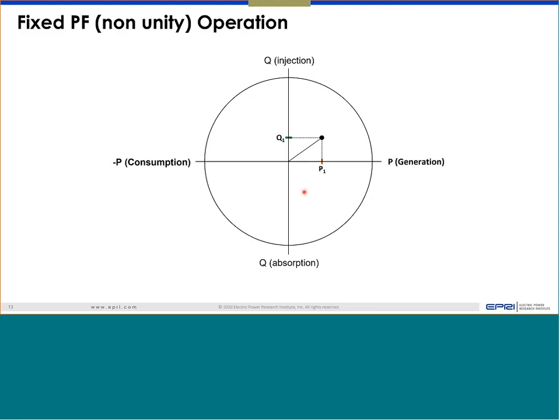Now, if the sun changes, the sun goes up, irradiance increases, power will go up. So power is increasing. But the inverter, this is the autonomous part. Once the power goes up, it knows that it has to maintain the power factor of, say, X, 0.97. So since power has gone up, reactive power also has to go up. It will automatically increase the reactive power to maintain the power factor until it hits the circle. So this S is the limit. This is the VA limit.